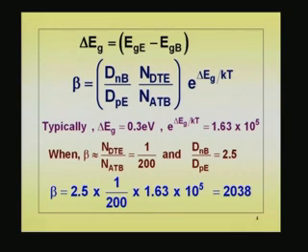In a conventional bipolar junction transistor, even though it is silicon emitter, silicon base, the band gap in the emitter is slightly smaller than that of the base, which actually can lead to the beta which is lower than what you get. You have ND in the emitter and base a big ratio, but this brings that down if delta Eg is negative. The reason, just I want to point out, because we are just in a conventional